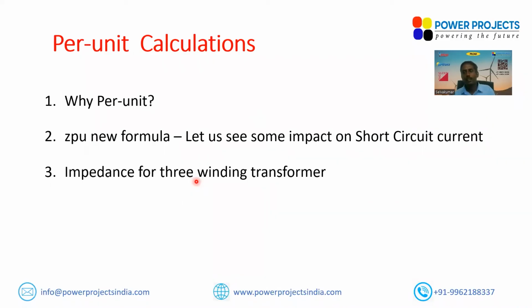I have seen cases where an EPC selected the impedance and ordered the transformers, and at the end, when the transformer is at site, what they had conveyed on the transformer impedance was on a different base MVA than what the manufacturer provided. This resulted in a huge short circuit current at LV, where the air circuit breakers available at the solar inverter terminals are not sufficient. Then they have to replace 100 air circuit breakers at site with a higher short circuit capacity.